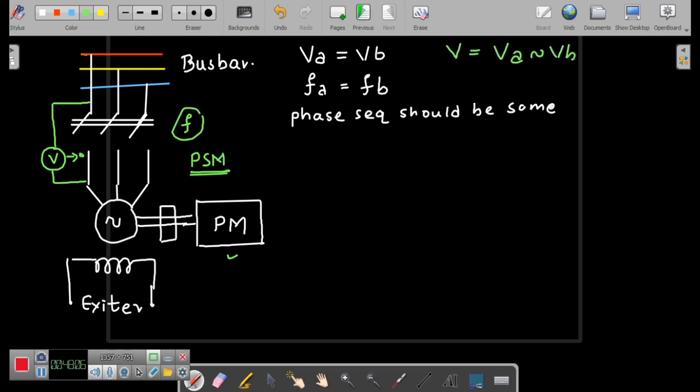This particular thing has to be executed in a sequential manner. First check the voltage, then check the frequency, then check the phase sequence. When all three conditions are satisfied, you close the switch. You take some action so that this switch is closed, right? This is the problem to be executed, and it has to be written in the form of a sequential function chart with the corresponding instructions, and even the ladder diagram should be drawn for this. These things we shall see in our next presentation.